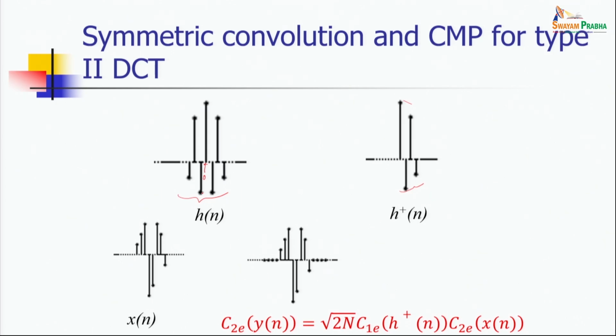So, once again, if I perform a convolution with periodic extension of these filter responses, where only half of the symmetric response is specified, I have to first convert it into a full response and then appropriately pad with zeros to inhibit the effect of excitations of certain length. Similarly, again appropriately pad with zeros.